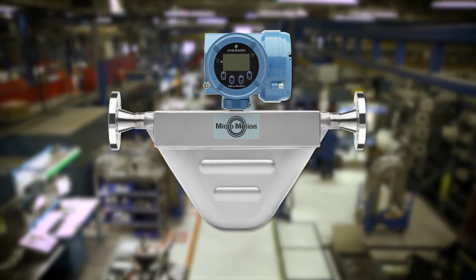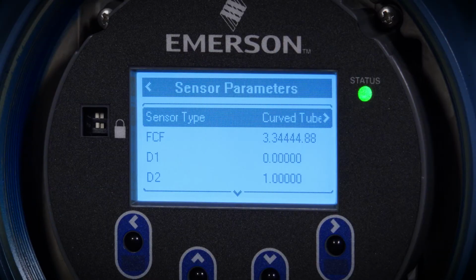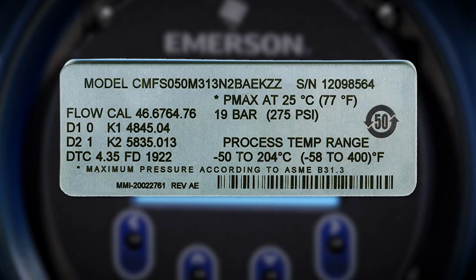If your transmitter was ordered with a sensor, it was characterized at the factory. However, you should still verify the characterization parameters. First, record the following calibration and characterization parameters from the sensor tag or calibration sheet: K1, K2, D1, D2, FCF, DTC, or sometimes labeled as DT and FD.